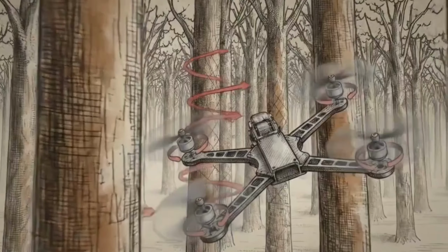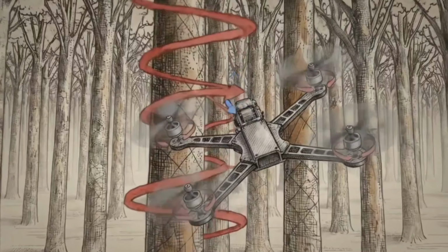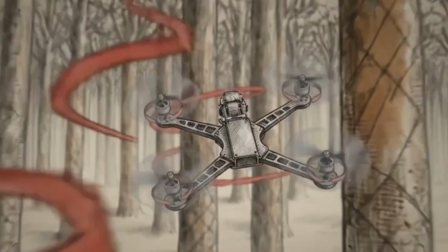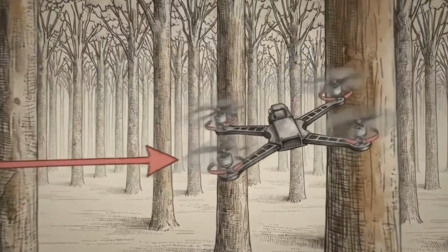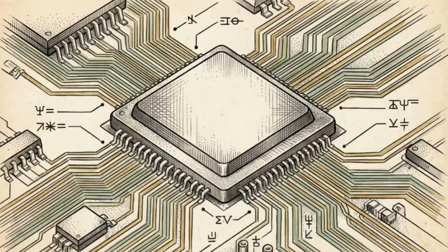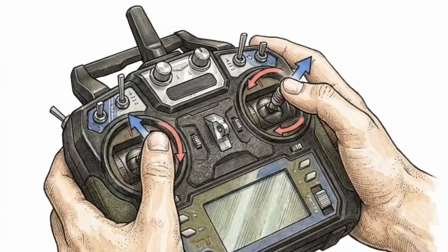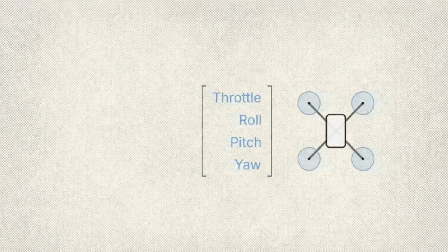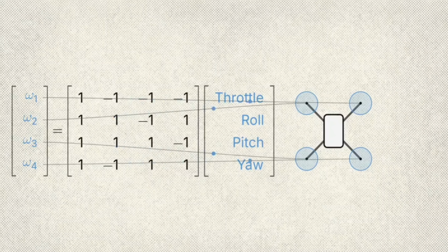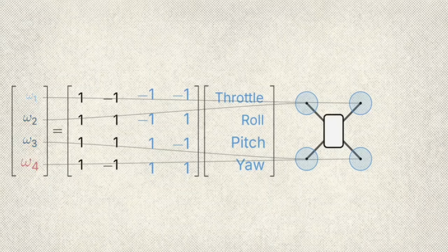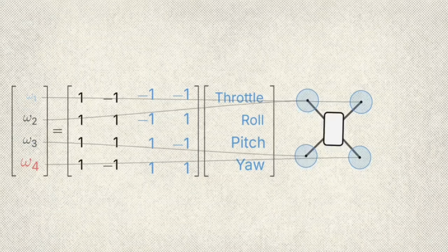In flight, a drone rarely executes these maneuvers in isolation. It manages pitch, roll, and yaw simultaneously while adjusting for variable environmental conditions. Managing these variables requires a flight controller. When an operator provides a command, that input must be translated into 4 specific motor speeds. This linear mixing matrix serves as the mathematical bridge between pilot commands and the RPM values for the 4 motors. It calculates compound maneuvers by summing the required RPM differentials for each axis, computing the resulting net value.